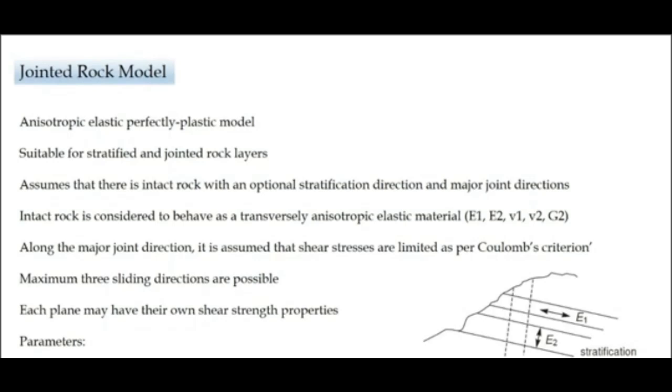The parameters which are generally required for analysis using this model are as follows. First, you will need the anisotropic elastic behavior properties for intact rock. That is where you'll have E1, E2, nu1, nu2, and G2.